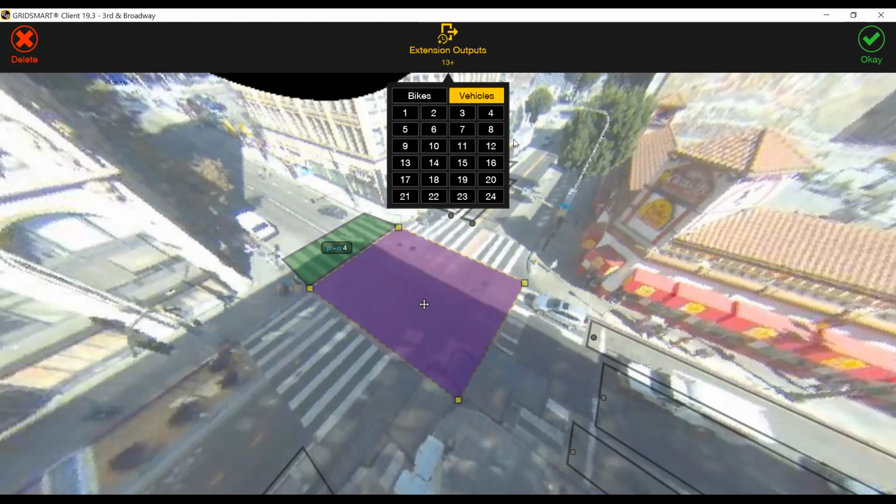Well, if you had transit or freight moving through, but you wanted to keep your minimum green time low, you can provide an extension on those. Maybe those left-hand turns on the side streets don't typically have a very long minimum green time. So we can provide a minimum green extension for a transit or freight. It's got a slow stop to start and might need a little extra time to clear. So we can provide that here in these vehicle zones.